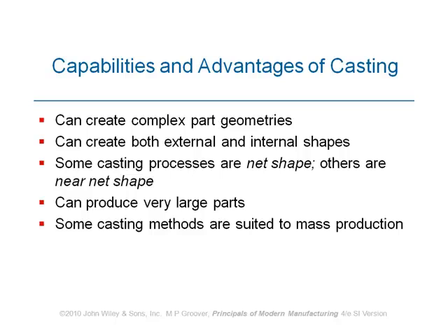And also, geometric accuracy of the part is low. And this makes it actually necessary sometimes to machine the part, or to subject the part which is produced in this method to some other processes, which are called finishing processes, in order to bring the surface of the part to a more desirable surface roughness or to increase the dimensional accuracy of the part.